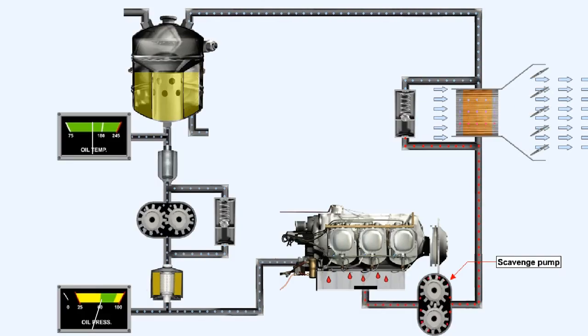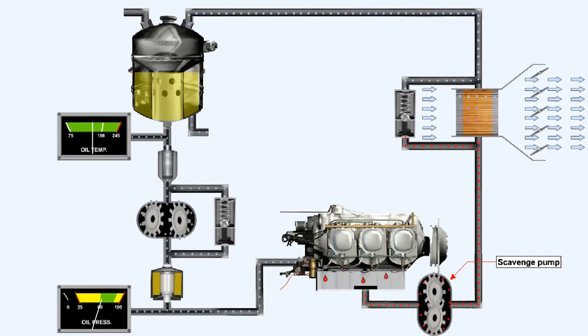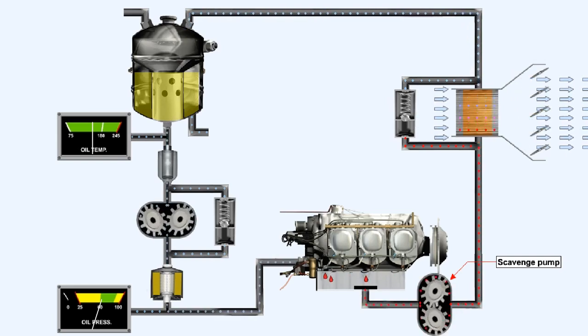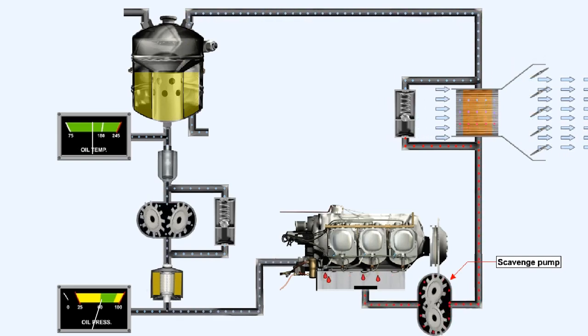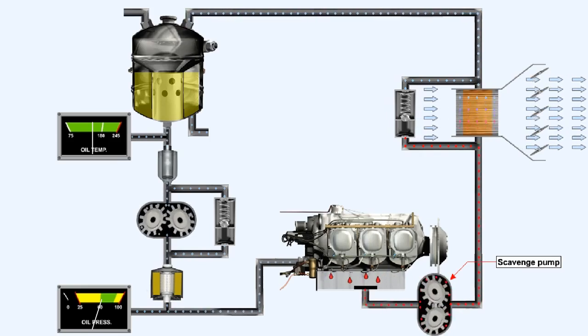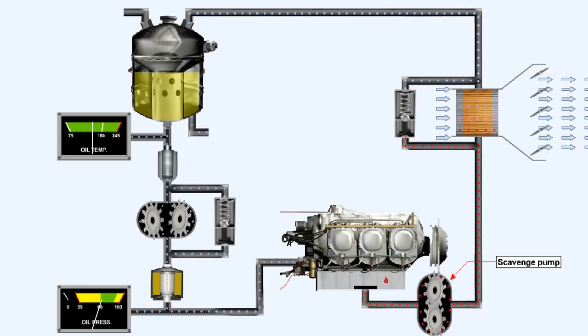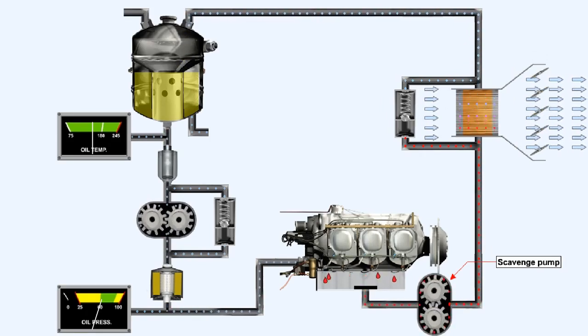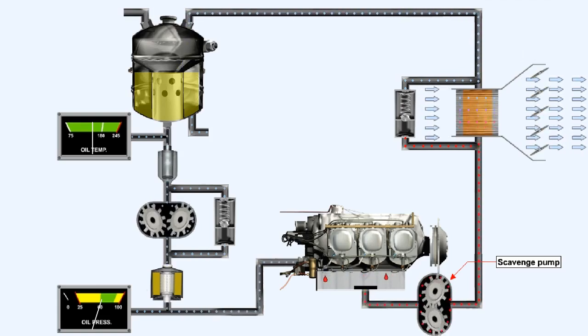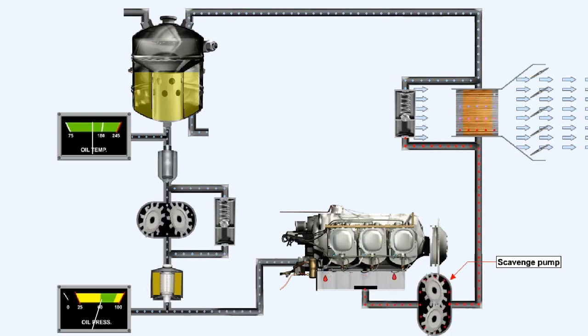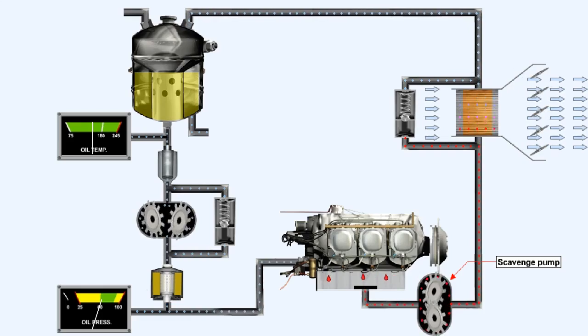As previously stated, the principle of oil supply is the same for both wet and dry sump systems. Both use the combination method of pressure and splash lubrication, after which the oil is returned to the engine sump by gravity. In a dry sump system, however, one or more scavenge pumps return the oil from the sump to the tank, to prevent flooding of the engine sump.